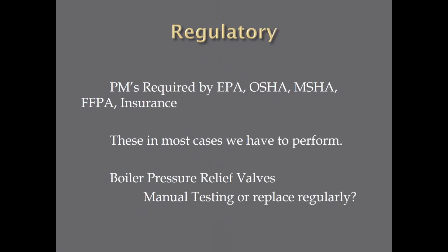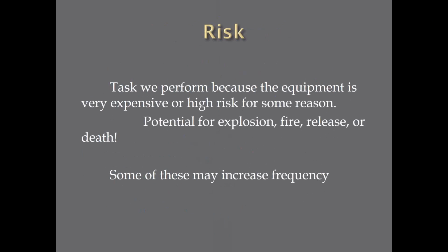Every year when we did the annual shutdown, I just replaced one or both of the pressure relief valves, sent them in for a rebuild inspection, and replaced them with new. But that was better than the valve leaking by and the leak getting worse as the year and a half went on. So again, sometimes with what's stated by law, maybe there's another option.